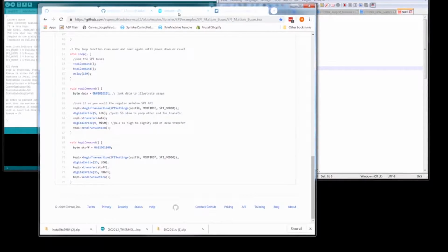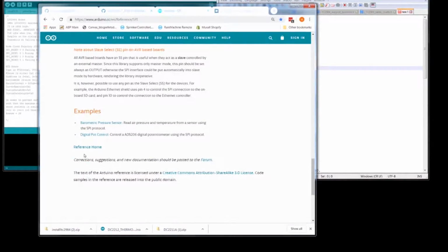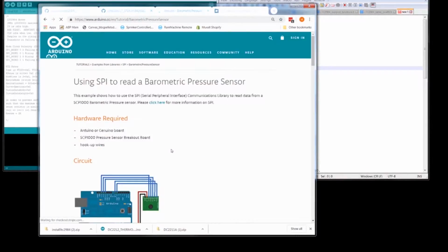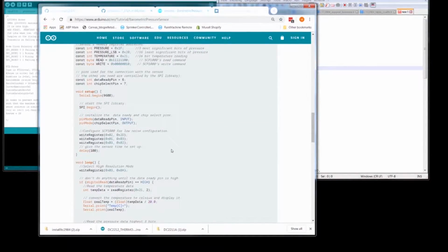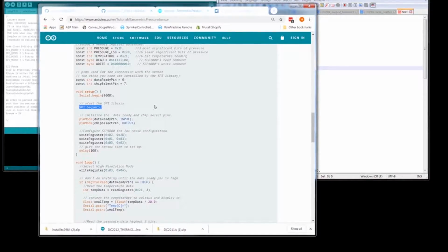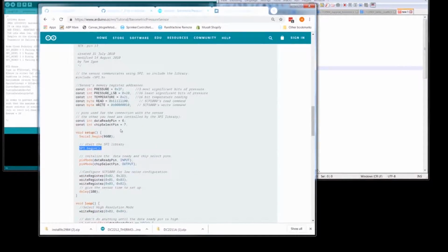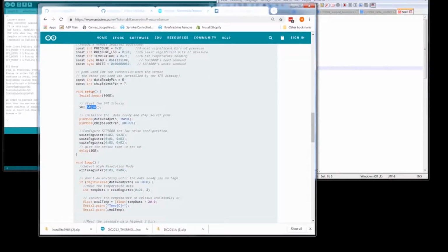So it's pretty nice. The Arduino right here, when you instantiate, let's go look at one of his examples real quick. I guess either one is fine. So here, yeah, you just do a setup, and then you just do an SPI begin. And there's no instantiating the SPI. You're just calling SPI begin from the Arduino library, and it instantiates an instance of it in the background, right?